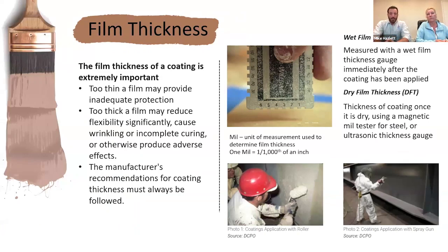The next thing, and this has always been a fun discussion for me, is film thickness. Many times I walk a job site and it gets brought to my attention, hey, Mike, it's very important that we have 2 coats. While that's a very common demand or expectation, I am more concerned about film thickness and whether that takes one coat or 7 coats. That's up to how you apply it.